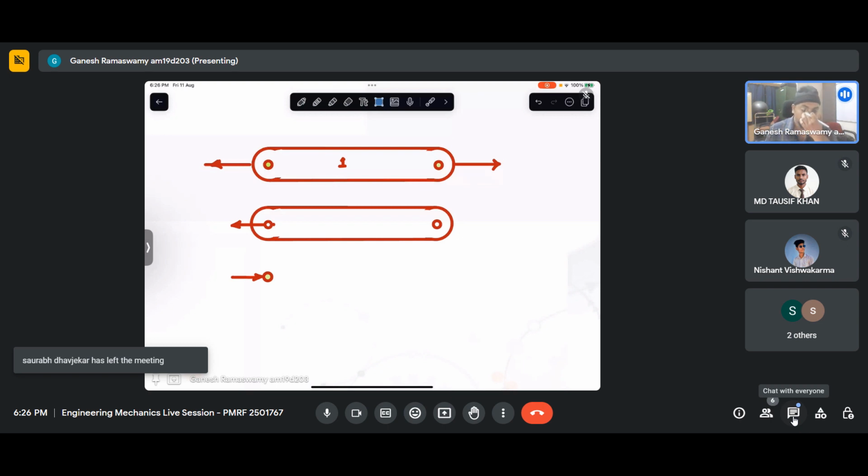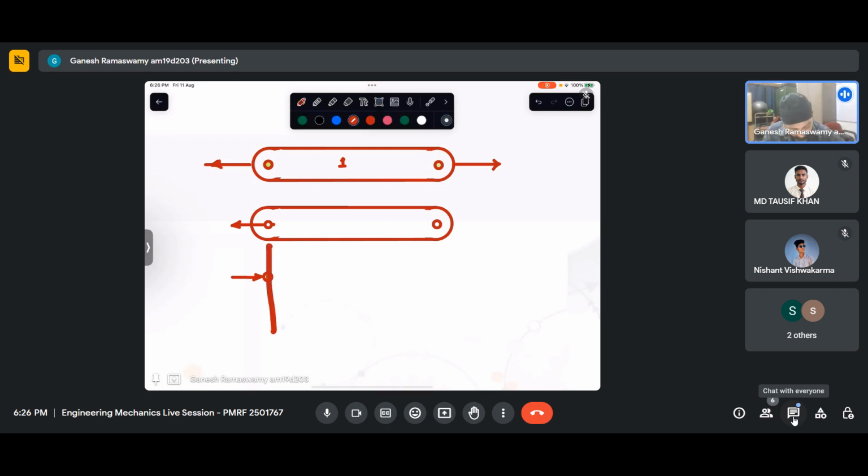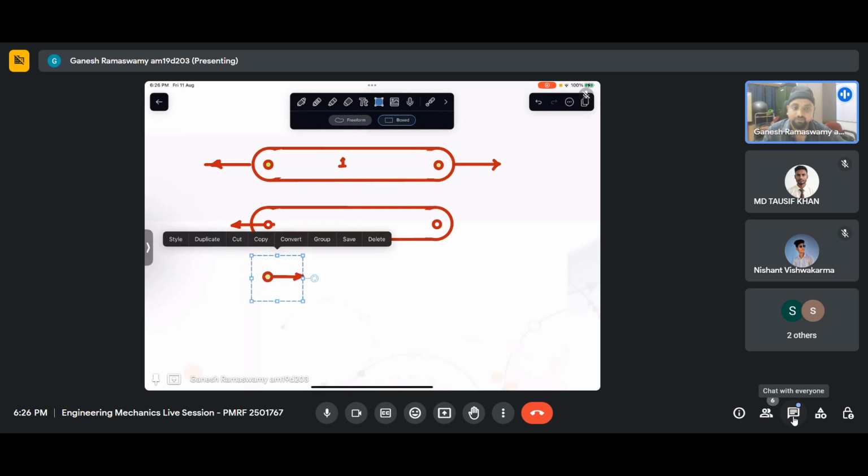So now if I have to have a convention, it has to be represented. For example, vectors, when we compare two vectors, it has to be with the same basis. Similarly, for truss analysis, we will follow a convention that we will rather consider forces to be on the same side of the member. Same side of the member means if I have a line like this, this is the member side, this is the other side. So if I have to put this in the member side, I can invoke that principle of transmissibility and I can put the force here with respect to the pin.